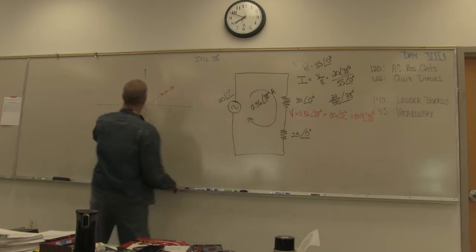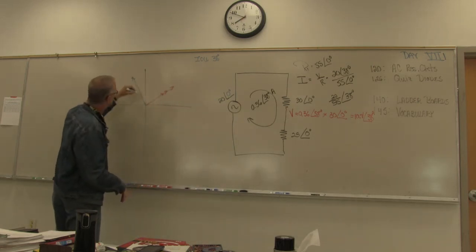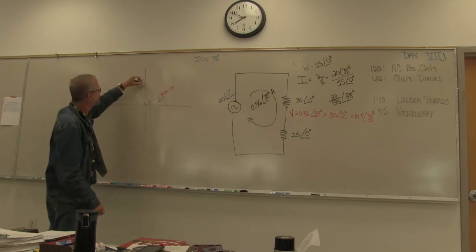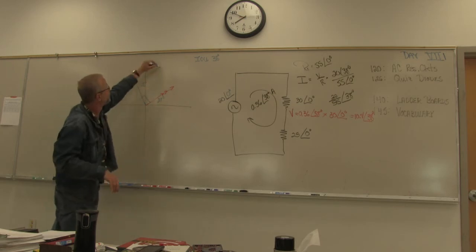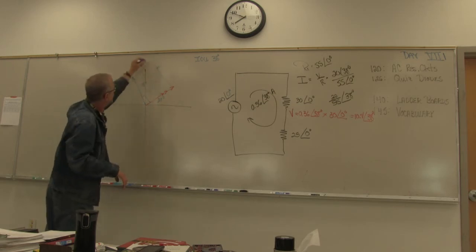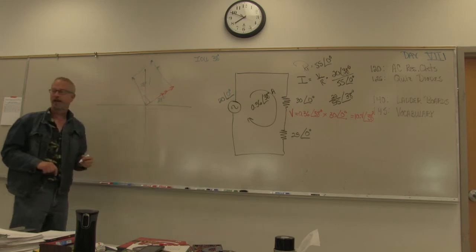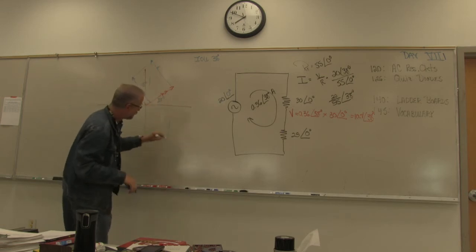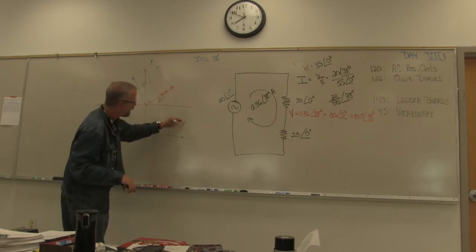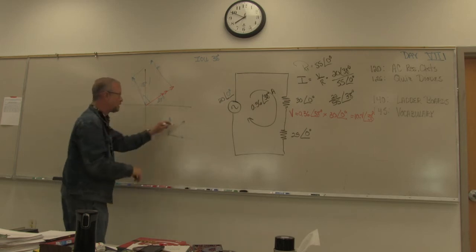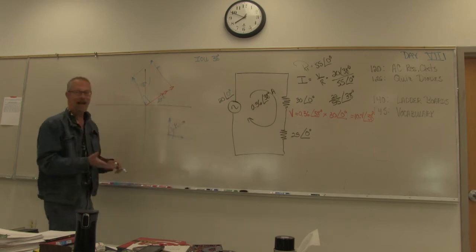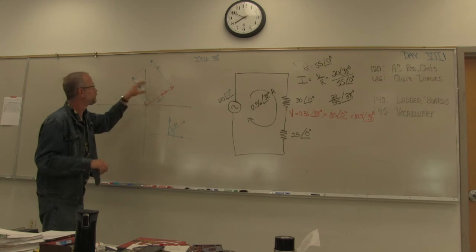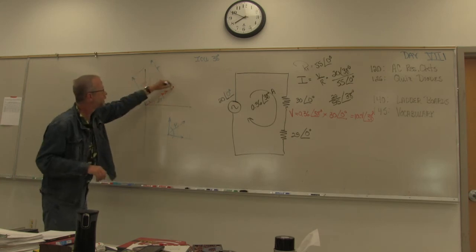If I have a situation where I have a 90-degree angle here, and this is 38 degrees, and this is whatever that would be, 128 degrees, and I've got something I want to figure out what that point is there, resolve those two vectors. Sometimes it's easier just to subtract the 38 degrees and approach it like this. Get this point, and once you've gotten R at whatever angle you have here, add the 38 degrees back in. It makes it easier than having to deal with these two things separately, both of them having an XY coordinate.